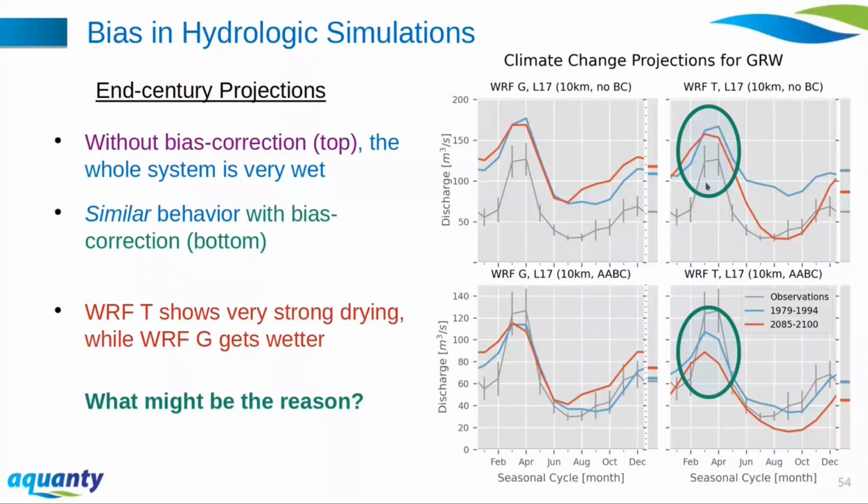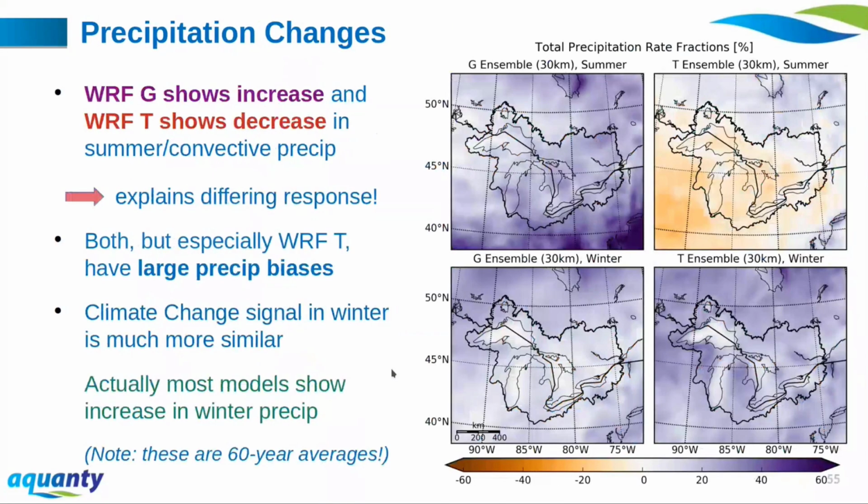Whereas in the scenario without bias correction, the system is still so wet because of the precipitation bias that you're not getting this recharge response, and it actually does all form runoff. So you don't get the drawdown of the groundwater because of the precipitation bias. And so, yeah, this is just an example of where you have to understand the processes and make a judgment of what you think is more realistic. And in this case, it's very difficult.